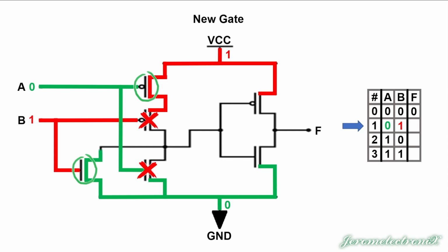It's got a path in through everything, and so it can go that far. It can go to the final NMOS and PMOS, affecting those gates. A 0 on a PMOS is going to allow flow, which means the high voltage is able to flow out through the gate.